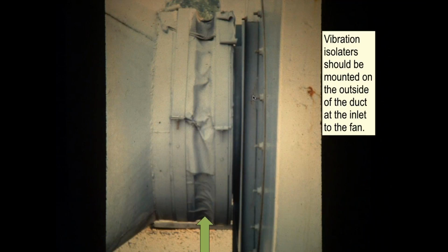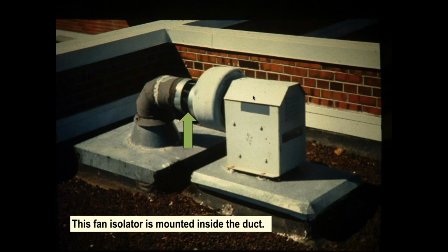So the revolutions per minute are about the engine. That motor rotates at 3,450 revolutions per minute. The blades may or may not. If you use a direct drive, they might. If you use pulleys or a gear drive, you can change the rate, going higher or lower than 3,450, depending on how you gear it. But usually when you design these systems, you're designing the motor to fit with the fan.